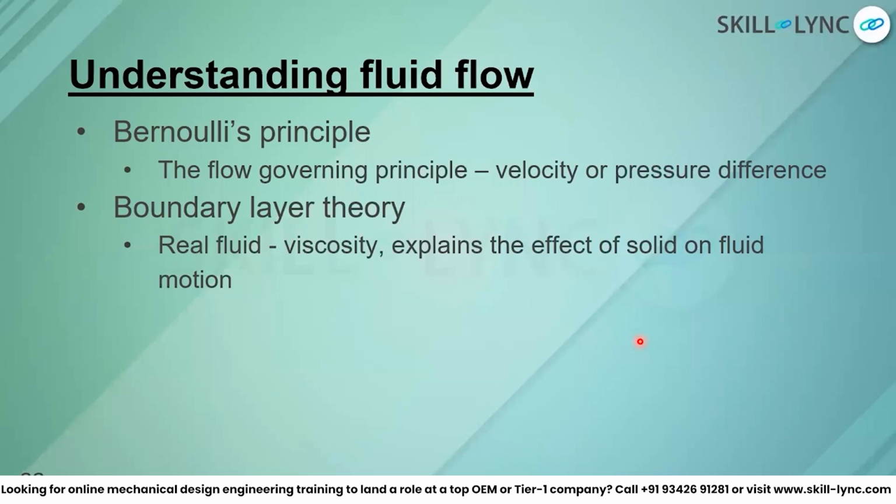There is something called validation of results: whatever you get in the post process, you try to understand whether the output is actually related to the input and expectation. You have certain rules and principles. If you're able to correlate them, then your results are good. If you're not able to explain those results, something is wrong.